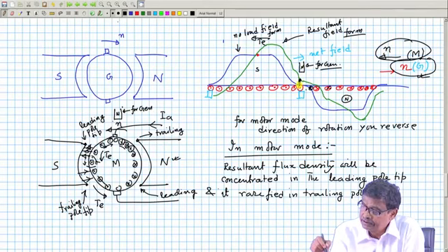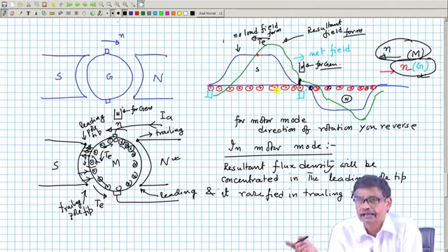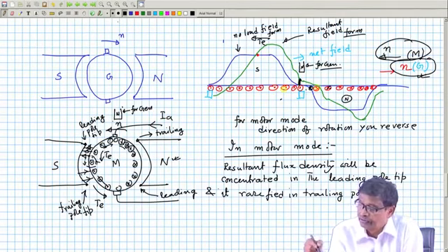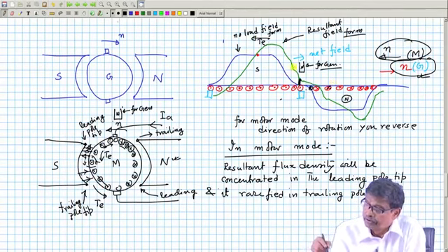Not only does it compensate, but it gives you a negative flux, like a north pole here, so that the conductor starts getting the feeling of what is ahead, generated voltage wise. So, it improves commutation, and these are the thinner poles.